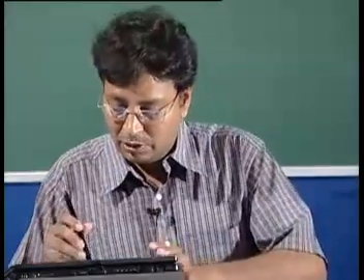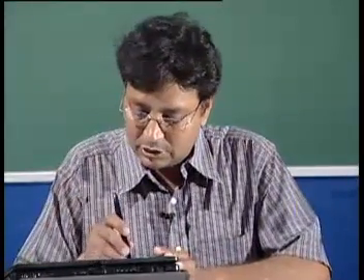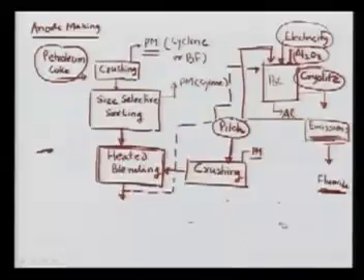All right, you see here in this process we are not baking the anode previously, but in fact the paste itself, as you see here in the dash form, is sent to the pot.